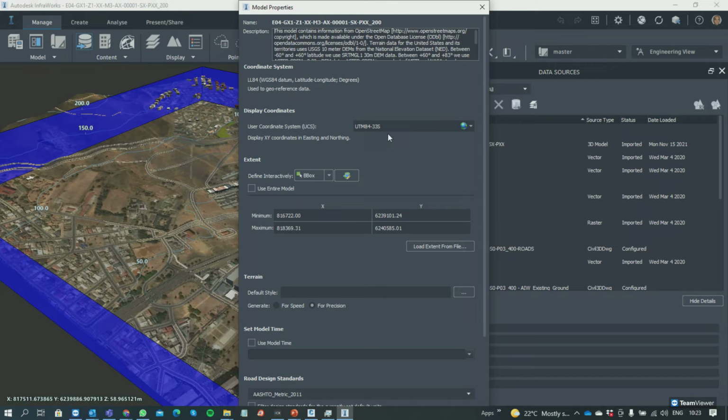So while it might not be as accurate as some of the South African coordinate systems, for instance, WGS84 Lo19, it does have the advantage that the X and the Y axes are aligned in a right-hand rectilinear sense. And in South Africa, I think Yemen and Vietnam are the three countries that I know of where they swap the X and the Y coordinate systems.